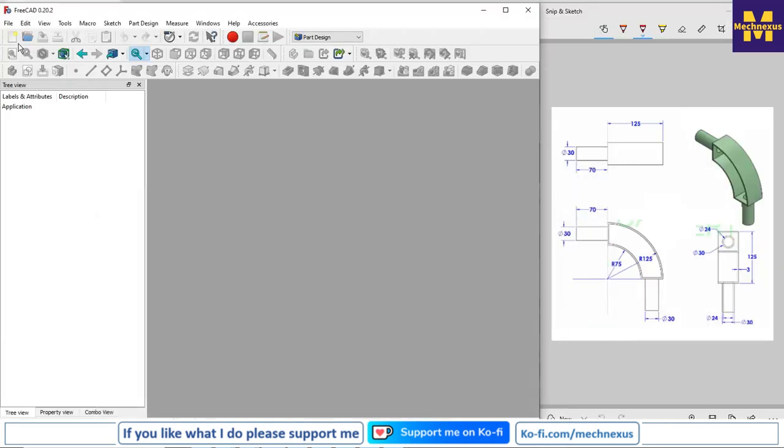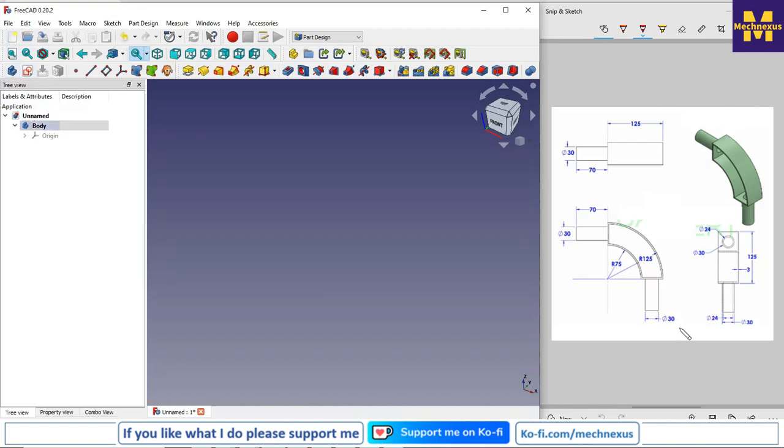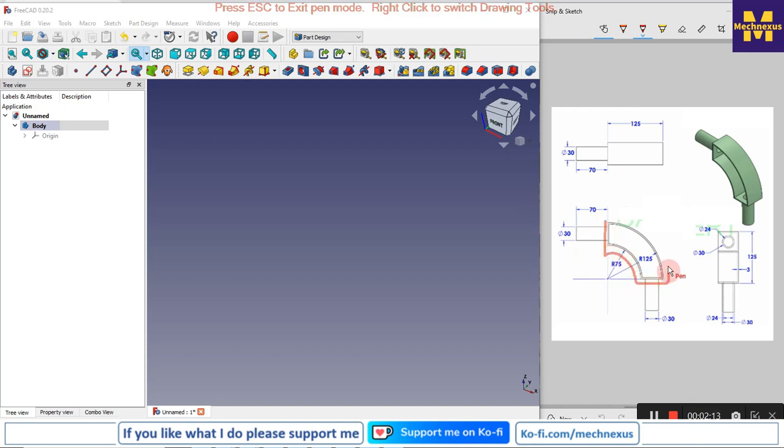So first I will create a new file, and I will create a new body, and we will read our drawing. First we will make this profile as a solid, and then we will use the shell command to remove the inside material. After that we will make these two pipes which should be hollow, and this tutorial's files you can download from the video description.